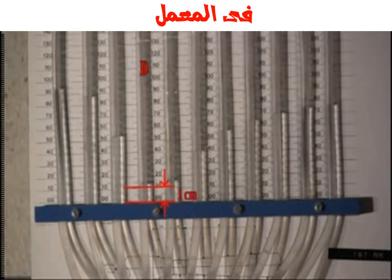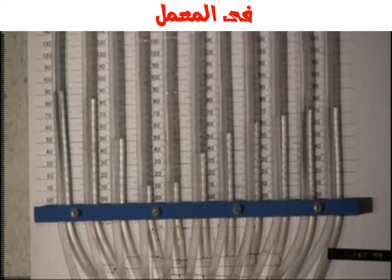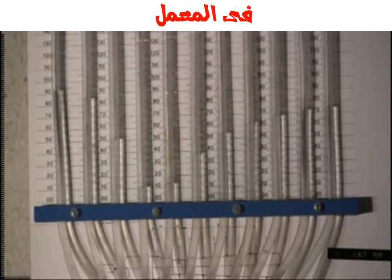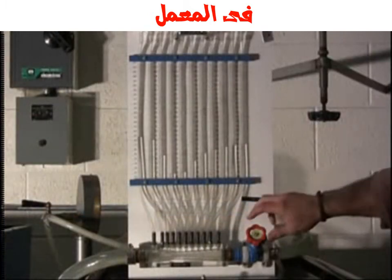Throughout the experiment, make sure that the water level in any piezometer never goes lower than 0 on the scale. Every time the flow is adjusted, wait for a few seconds in order for it to stabilize. Take note of this reading at station D. Next, we will set the flow to a minimum.